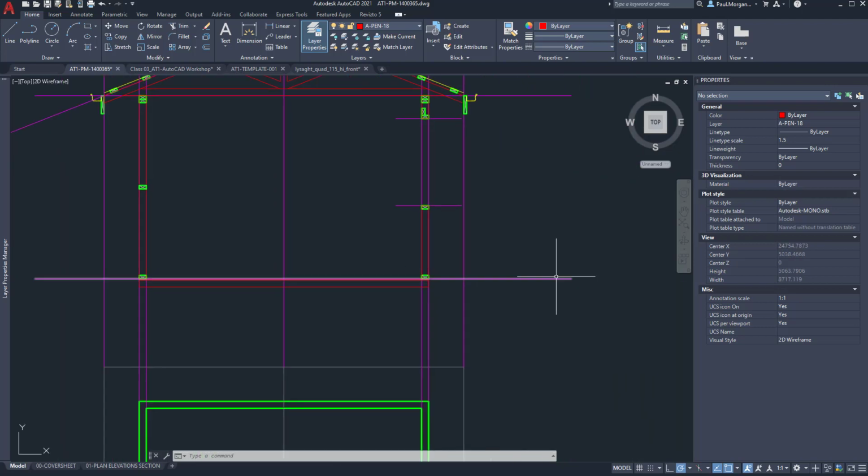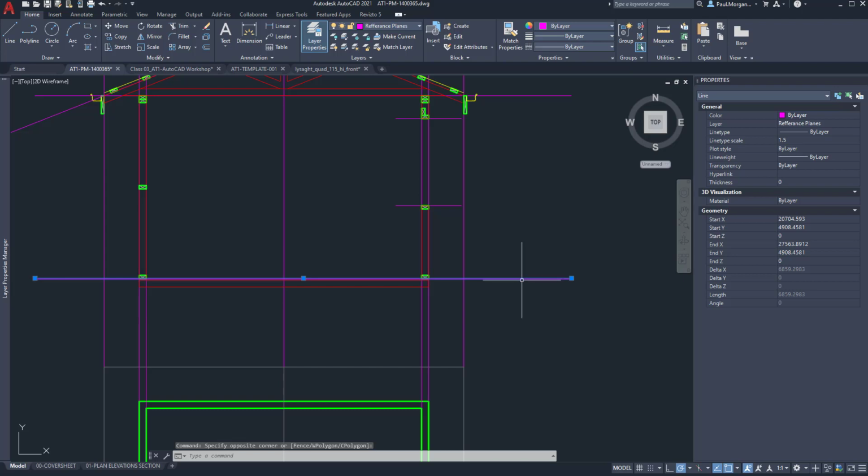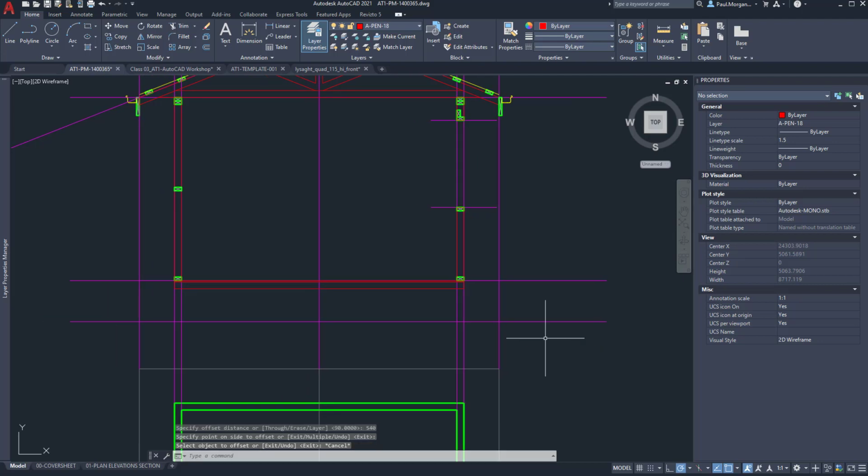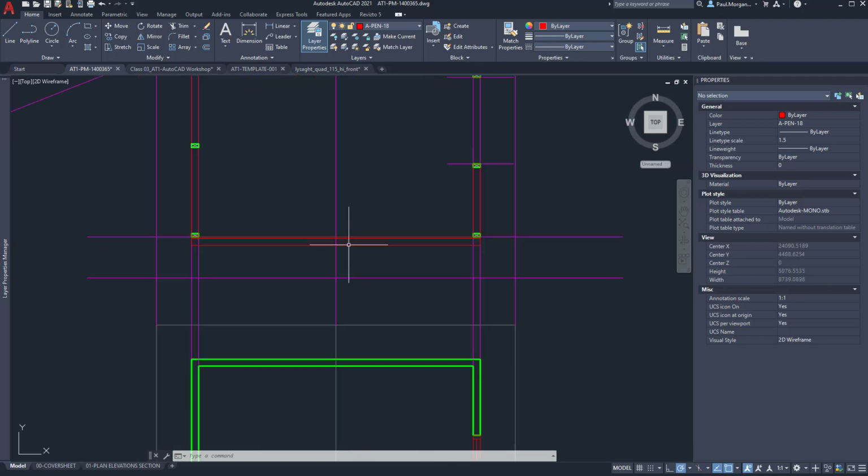Okay. Now we know that from this point here, the finished floor level, we have an offset of 540 mil, which is the ground level. So between here is our natural ground level up to the finished floor where you would actually stand if you were standing inside of this building.